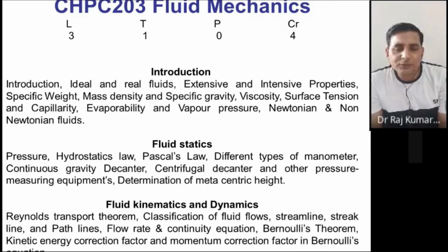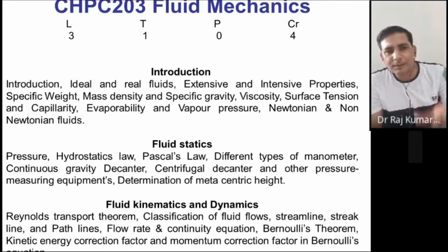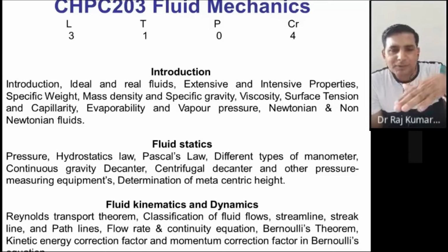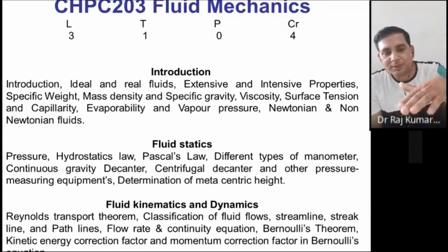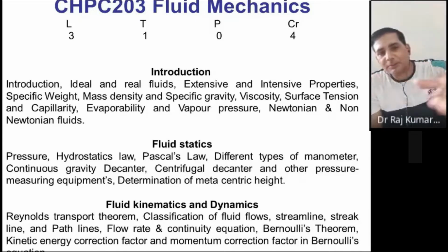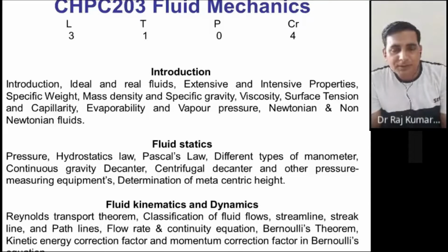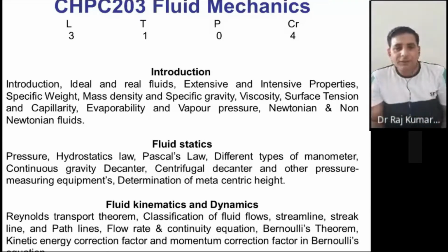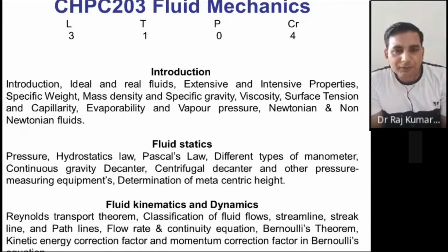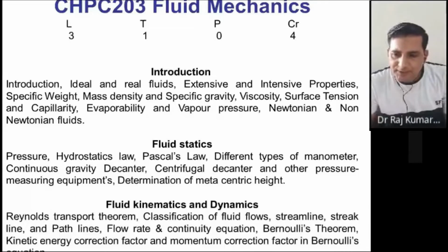The second part is that sometimes you want things to be submerged. Submerged means it should be completely in the fluid, level with the top surface. That can only be possible if the densities of the two systems are the same. If your density and water density are both the same, you would be floating at the top surface only, completely leveled, right? If your density is too high, you are going to sink. So to decrease the density, you can increase your volume. That's where you design your floating body systems. So these are the topics that would be covered in your statics part.